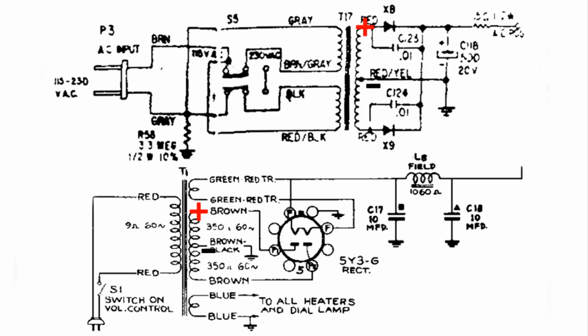the top rectifier in the solid state is going to conduct, and in the tube power supply, the rectifier that's on the left is going to conduct, and we're going to have this, and both are going to be charging their electrolytic capacitors. Now I'm only showing one in the tube power supply, but of course capacitor A would be charged also.